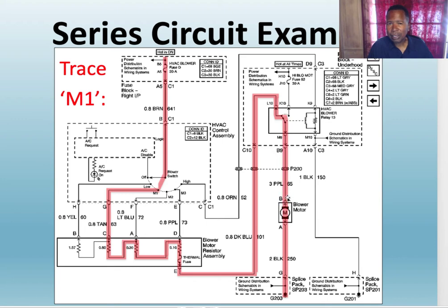Now, right here at terminal B, this male connector, did you think we still had 12 volts here? Remember, I went through 3 different resistors and dropped the voltage. At this point right here, the increased resistance will cut down the voltage through the load device to ground. And this motor right here will run much slower, because it had to feed through up to 3 resistors.